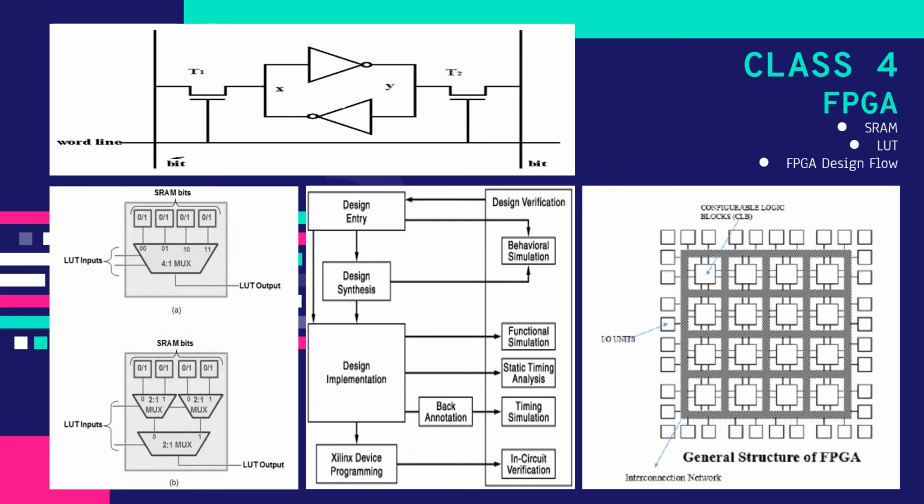We then moved on to the LUTs, or the lookup tables, which are analogous to logic functions implemented using a 2 power n to 1 mux. If you have two inputs using an FPGA, you can program the LUT as any gate to operate on the operands A and B. They can also be erased and used as a different gate. It basically consists of memory and a mux. The number of input variables will be the number of LUT inputs. While realizing the function using an FPGA, the value of the output variables for each of the combinations will be